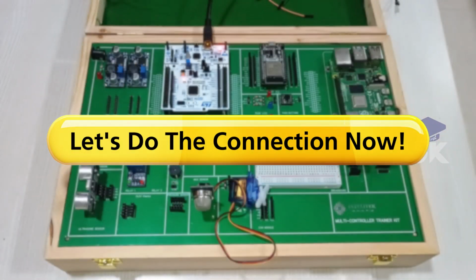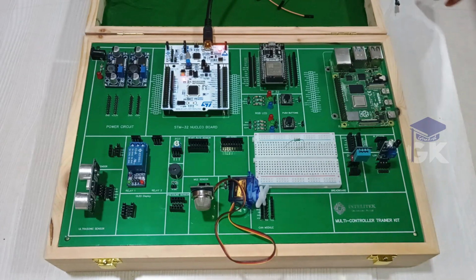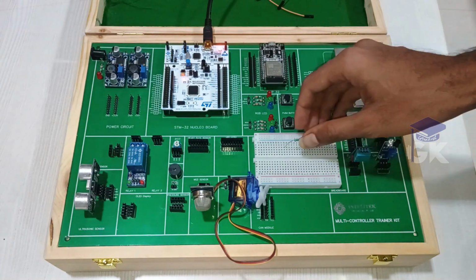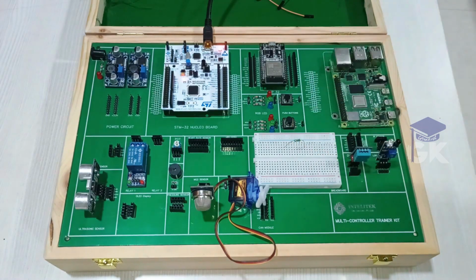Let's start with the hardware connection between the push button and the LED. In ESP and Arduino Uno, we have also used a push button, but it internally pulls up the push button. But in the case of STM32, it does not do an internal pull up, so we use a resistor of 10 kilo ohms or 4.7 kilo ohms to externally pull up the push button.